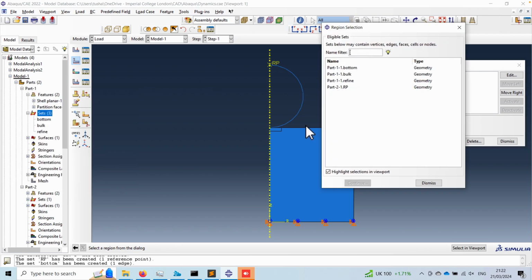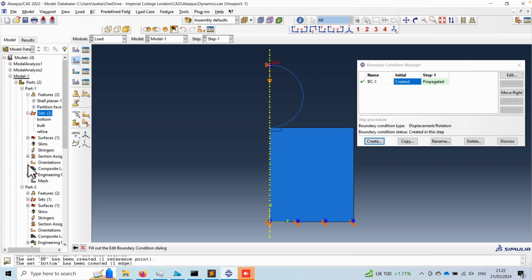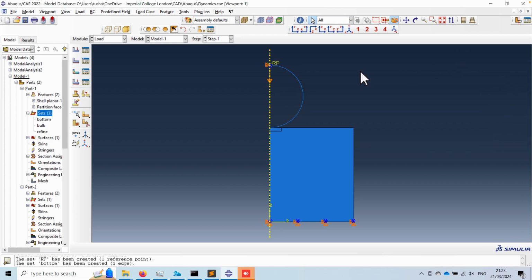We can do the same thing by applying some force as well, so that's not a problem. Okay, we want all other displacement other than the vertical to be 0. So for vertical we choose a small value of say 0.01. Okay, so as you can see, it will not move horizontally, it will not rotate about the z axis, like in plane rotation is 0, but it will only apply a vertical downward displacement. Okay, after we do this, now our model is ready.